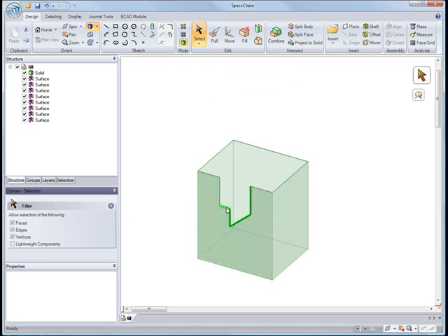And in a similar way I'll select on these edges and fill them in, and watch as it fills that gap in the surface. I could also select on the top loop of edges and fill it in to cap this surface and turn it from a surface into a solid.